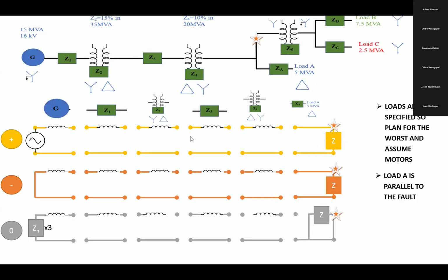All right. Let's start here. The yellow one is the positive sequence. Orange one is the negative sequence. Gray one is the zero sequence. Okay. Now this is a generator, a Y connected generator. So you have to put it solidly grounded. So there is no ground connected here. Okay. Positive sequence comes with the source. Negative sequence comes with only impedance. Zero sequence comes with the impedance, but the Zn must be represented here, but later we can short circuit it if there is no impedance.